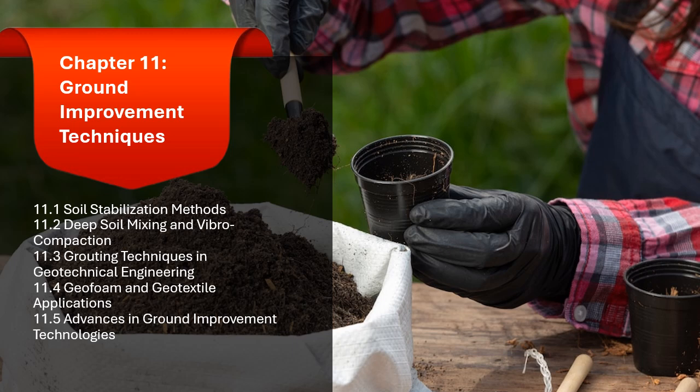1.2.2.2 Applications of vibrocompaction. Improvement of loose sands. Vibrocompaction is especially effective in improving loose sandy soils that are prone to liquefaction or excessive settlement. By densifying these soils, vibrocompaction increases their load-bearing capacity and makes them more resistant to seismic activity.